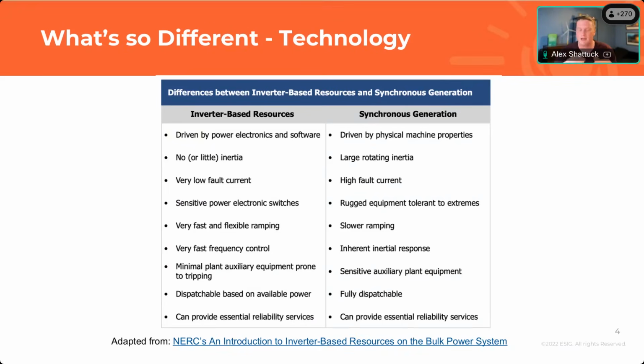That's a huge difference in mindset and thinking. A synchronous machine is pretty predictable, and it's probably going to do the same thing for the life of the facility. With a software-driven power electronics interface device, a firmware update can accidentally change that performance. One parameter could change performance massively, and tracking those things is very important.